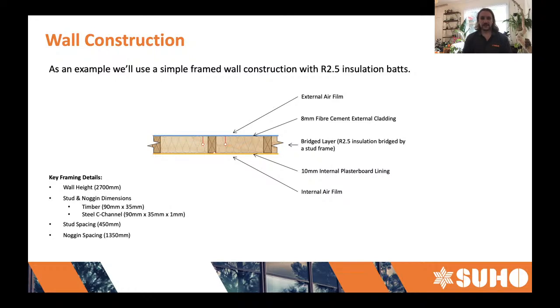Now, the New Zealand standard 4214 is the isothermal planes method for calculating thermal bridging. That means that we consider each of the layers that are continuous, as we did for 2016. We add up the external air film, which will achieve 0.04.